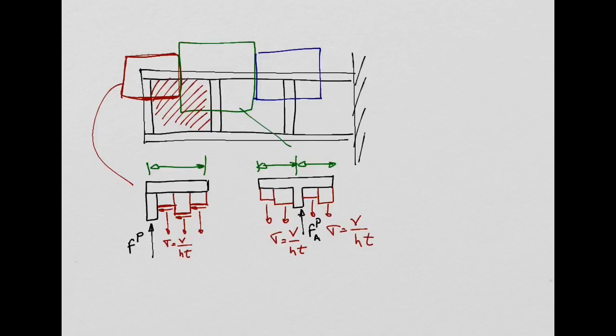If I look at this web, half of that developed diagonal tension field is going to the post at the tip of the spar, and the other half is going to post A. Yeah? So in that case, I will say that this dimension here is going to be 400 over 2. Same thing for this one, 400 over 2. Yeah? Make sense?